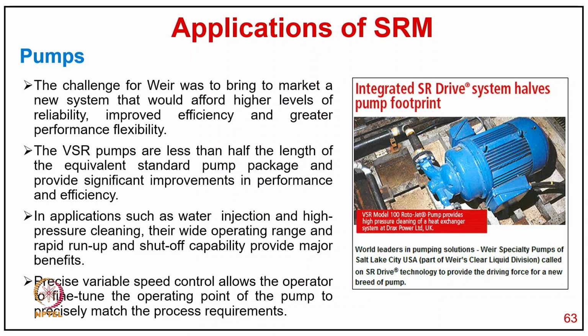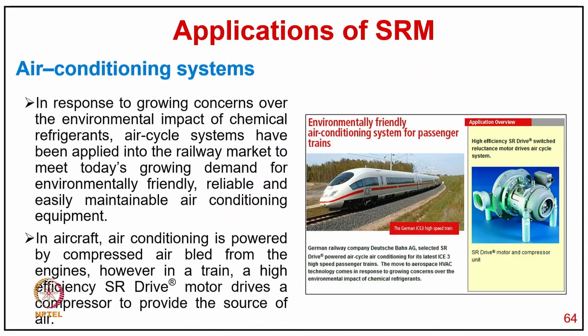In applications such as water injection and high pressure cleaning, their wide operating range and rapid run-up and shut-off capability provide major benefits, and precise speed control allows the operator to fine-tune the operating point of the pump to precisely match the process requirement.